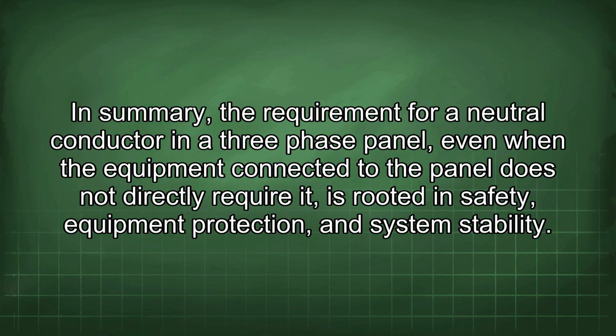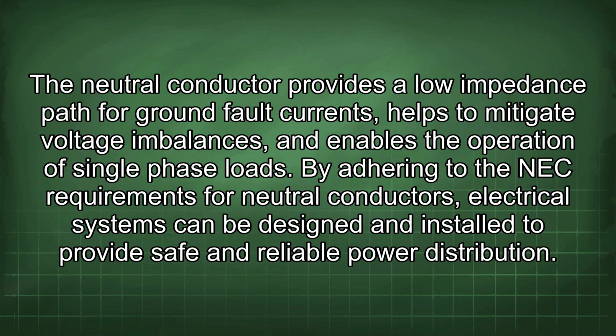In summary, the requirement for a neutral conductor in a three-phase panel, even when the equipment connected to the panel does not directly require it, is rooted in safety, equipment protection, and system stability. The neutral conductor provides a low impedance path for ground fault currents, helps to mitigate voltage imbalances, and enables the operation of single-phase loads. By adhering to the NEC requirements for neutral conductors, electrical systems can be designed and installed to provide safe and reliable power distribution.